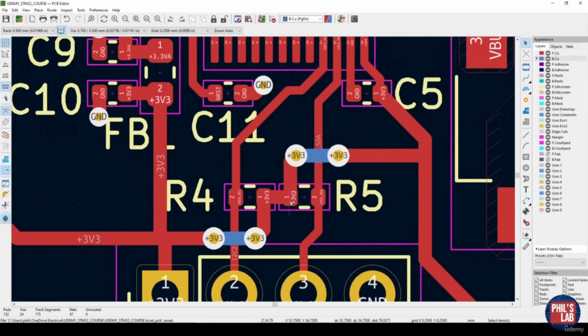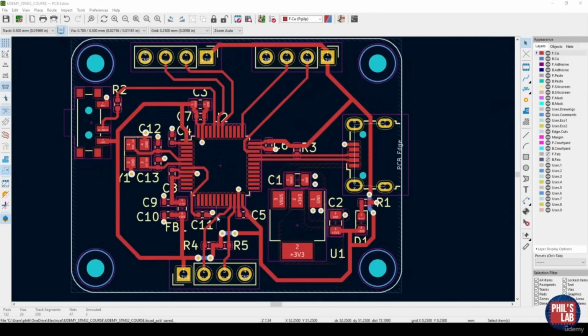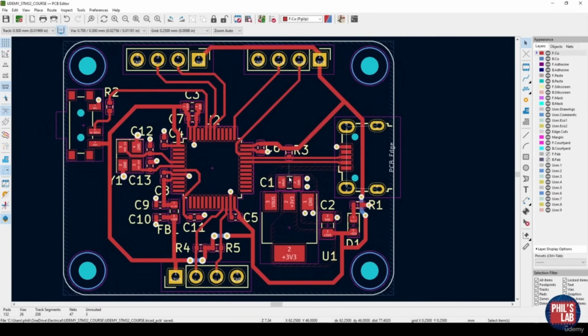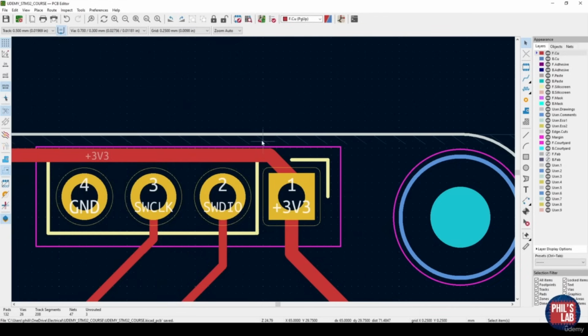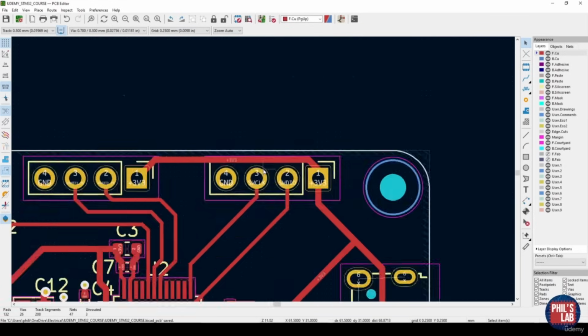What you can also see, I'm using slightly larger vias, so the KiCad default vias for my power, and this is typically good practice, especially if you're going into higher current designs. And there we go, I've now finished routing these 3.3 volt rails. You can see it's perfectly fine to route this for these lower speed designs, and make sure you do the smallest amount of jumps as possible. So for example here as well, I'm pretty close to the board edge, and you wouldn't want to go any closer. But this is fine, at least I didn't have to cut the ground plane.